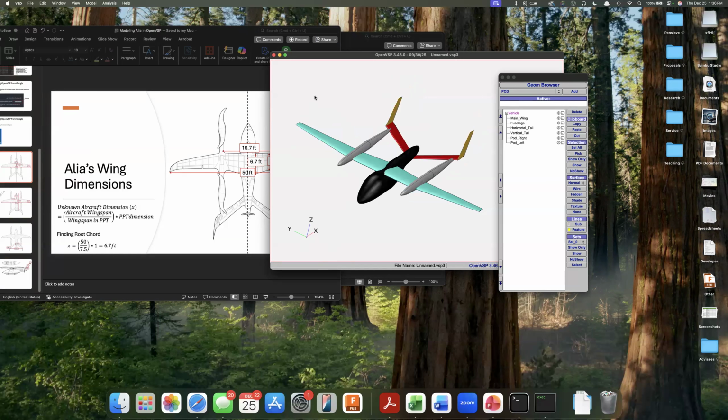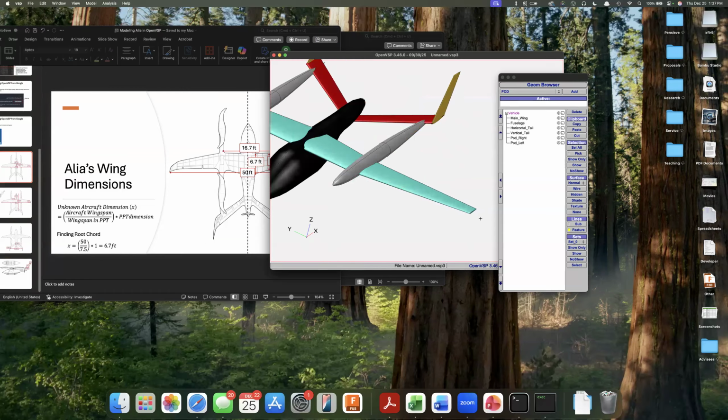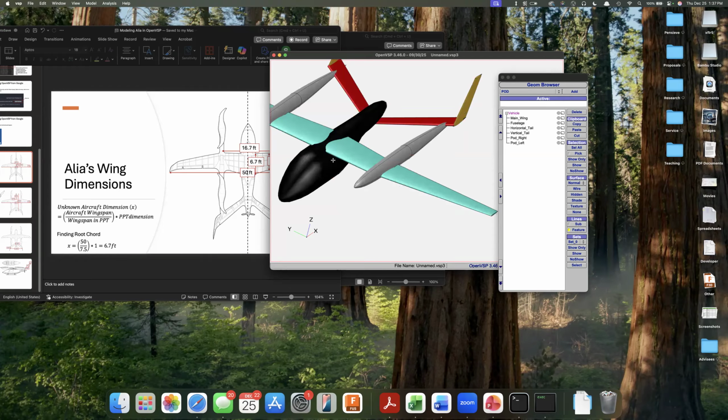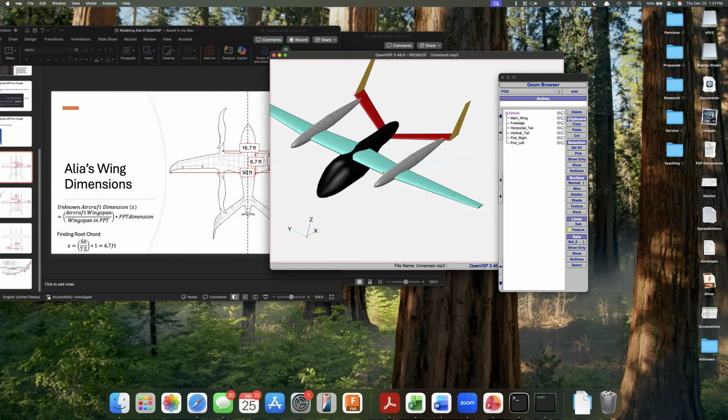Hopefully, this is useful. I'll create another video showing you how you can run some basic aerodynamic analysis in the same software. It's also pretty simple to do, and you can get lift, drag, etc. Oh, before I forget, I do want to tell you one thing that is very, very important, right? If you're going to improve performance, the main way you can do that is through careful selection of airfoils for the wing and the tails, right?